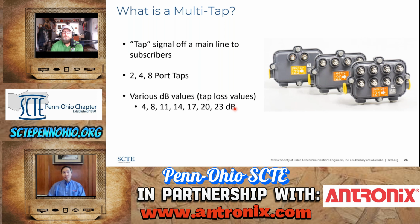And that is due to the upstream path loss that's also considered in the taps. On the one-way only system, where your upstream transmit level was not a consideration, high value taps of 29 and 32 were not uncommon. But over the years, that number continues to go down. Correct.